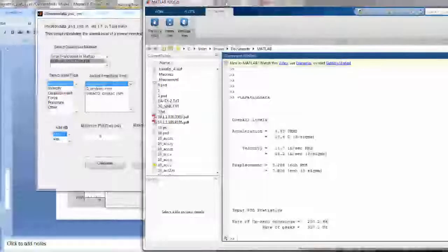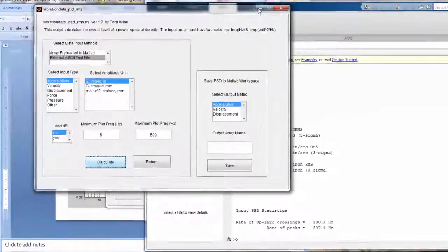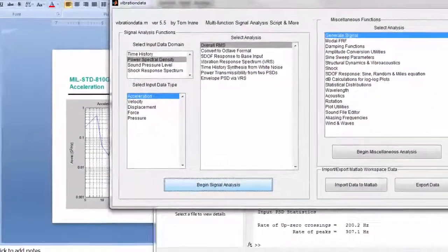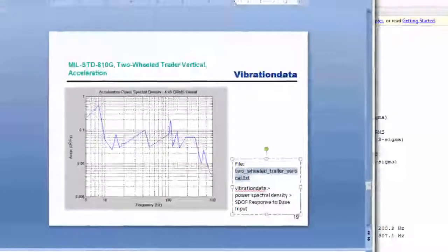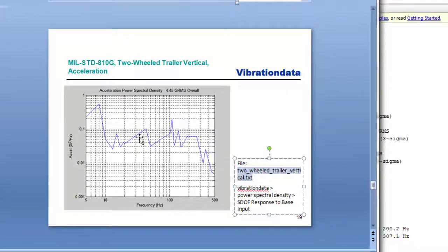Or another thing that we sometimes get in the habit of doing is we might say, well, the natural frequency of our components is 50 hertz or higher, so what's going on at 10 hertz and lower doesn't really affect as much, so maybe we'll just cut off at 10 hertz to limit displacement. Well, that might require writing some waivers and going through some review boards and everything.